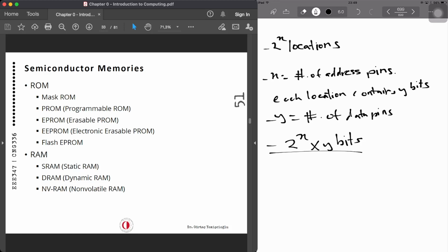The shorter this elapsed time, the better and consequently more expensive the memory chip is. The speed of the memory chip is commonly referred to as access time, and it varies from a few nanoseconds to hundreds of nanoseconds, depending on the circuit technology used in the design and also in the fabrication process.